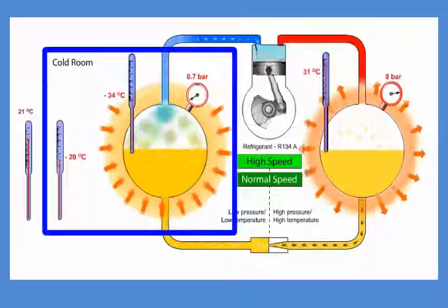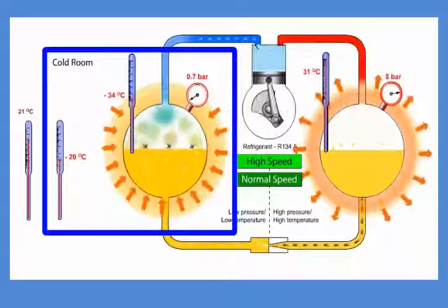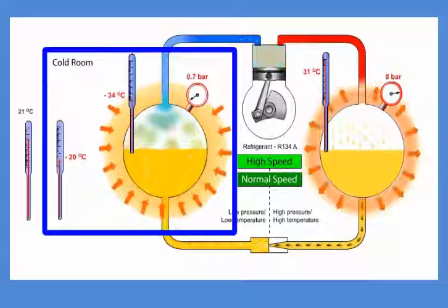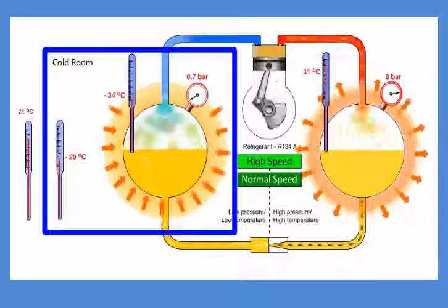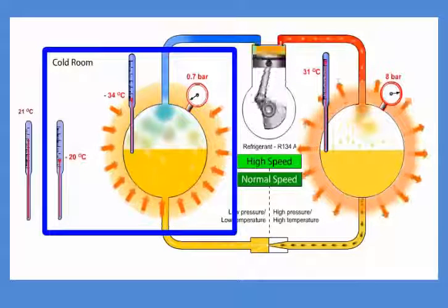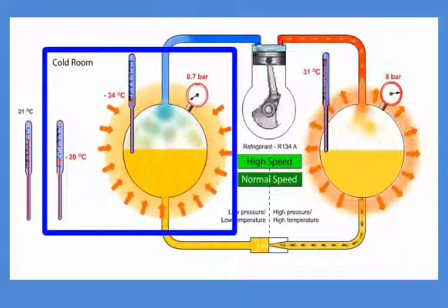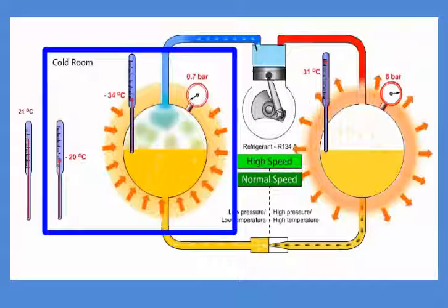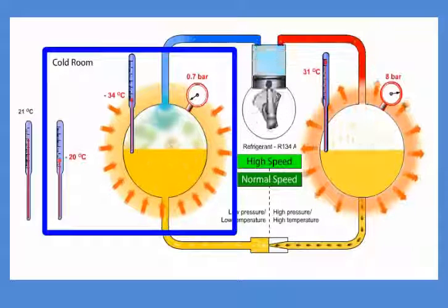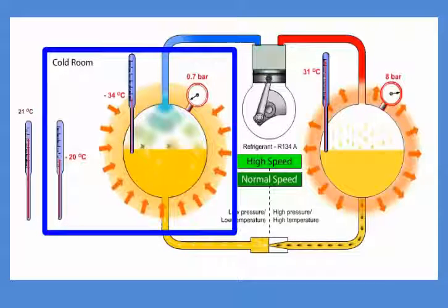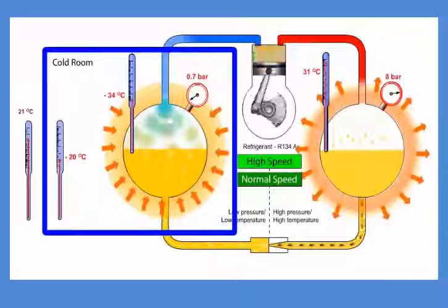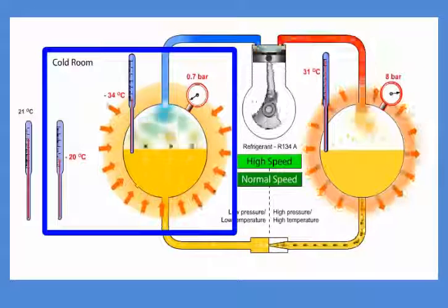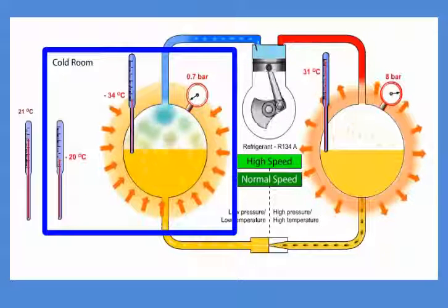When the compressor delivers more refrigerant to the condenser flask, the consequence is also that the pressure and temperature in the condenser flask goes up, and the condensation process gets more violent. Now that the temperature in the flask is higher, the heat transmission to the ambient will increase because of the higher temperature difference. A new equilibrium will occur when the heat transmission energy streaming from the flask wall to the ambient is the same as the energy changing phase from vapor to liquid.